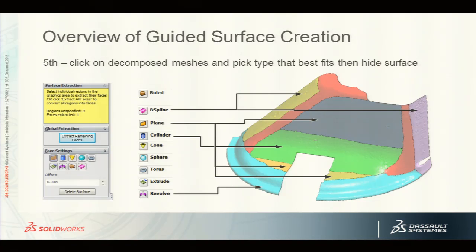These are going to be fillets in my final model, so I don't care about those areas. I'm going to apply fillets in the final parametric SolidWorks model to represent those. But what I do care about are these larger areas, like the blue planar face, the green cylindrical face, the revolve.